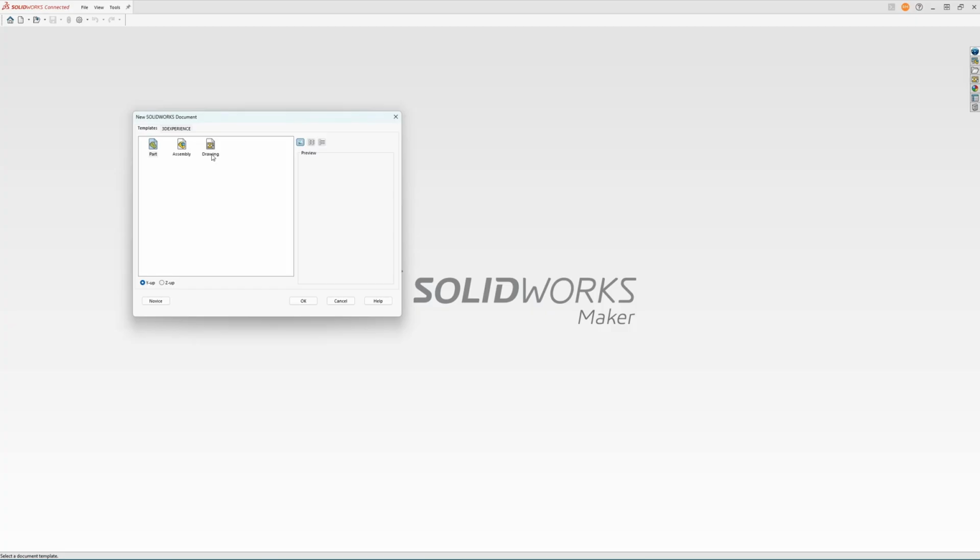and these are local on your computer. And templates are basically a kind of start arena for your parts or assemblies or drawings. You can make a new template yourself by just opening a part, changing whatever settings you would like to change, and saving it again as a template. And then next time you open it up, you have the right settings that you like. An example is units. So if you're working in imperial units, you can change your part document settings for that, and so on. So let's create our first part here.